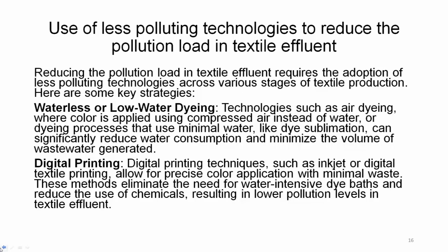Waterless or low water dyeing technologies such as air dyeing, where color is applied using compressed air instead of water, or dyeing processes that use minimal water like dye sublimation, can significantly reduce water consumption and minimize the volume of wastewater that is generated. So, somehow if we can adopt waterless or low water dyeing procedures, that would be the most ideal situation.